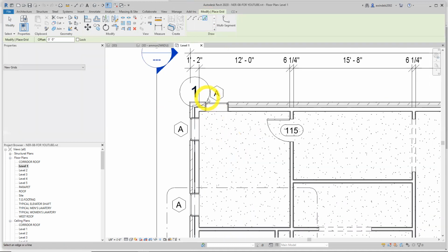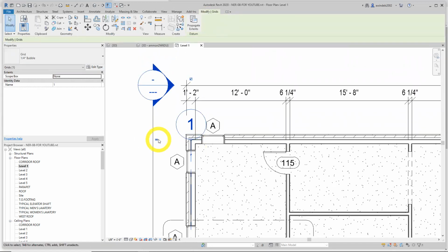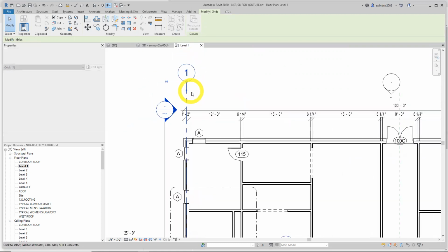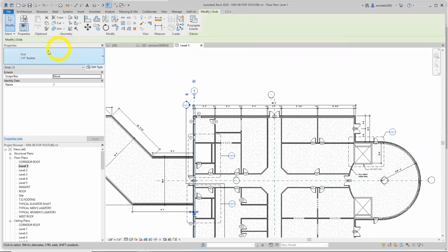And we're going to have to adjust it. So let's hit escape twice, which I just did. 3D meaning that it's in all views for the most part in general. 2D meaning it's specific to a view. 3D, it's more of a model item. So I use this grip to move and slide. This checkbox to turn it on and off. We still have only the grid bubble selected.